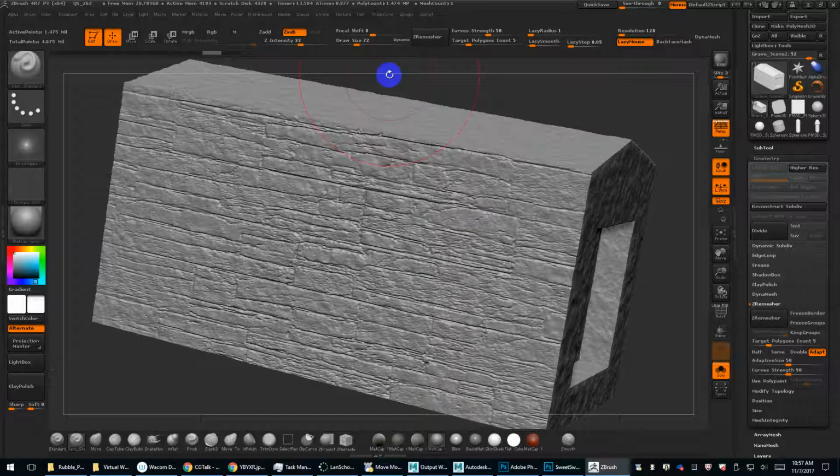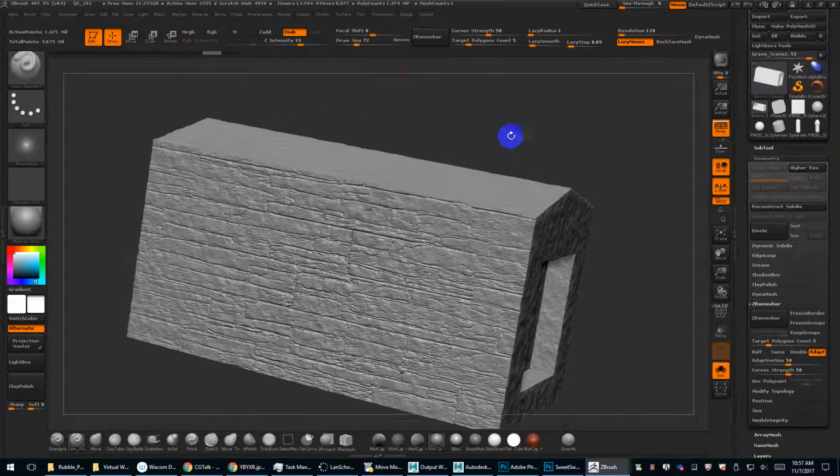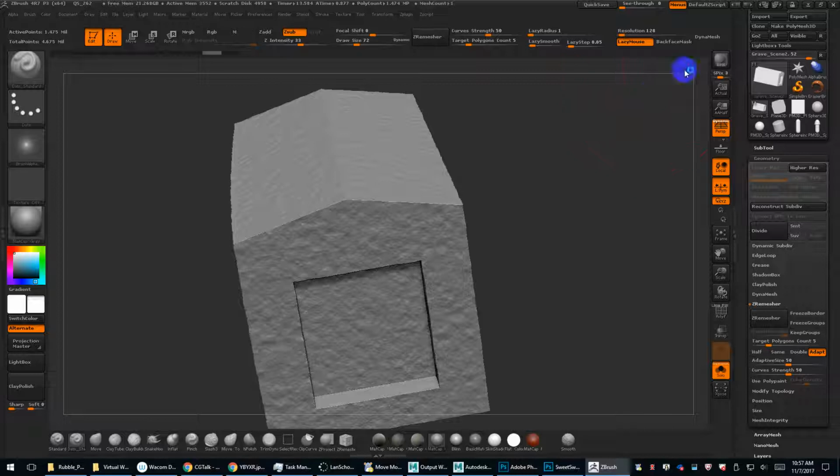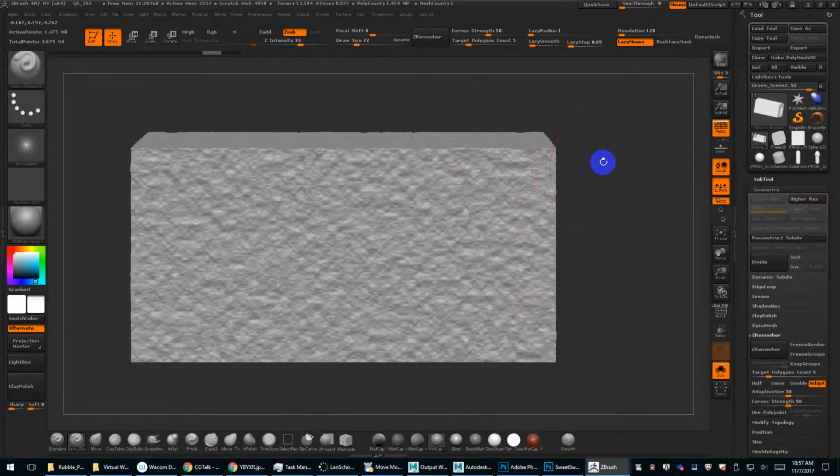So if you find your scene getting really, really slow, and even if you're hiding parts like a building or one of the props in your set and it's still getting kind of heavy, again, I always save a version. So I'd say version 3 of the scene, and then immediately save version 4, and then do the decimation, because you always want to have at least a base copy of those objects pre-decimation, because once you decimate, it's hard to get that detail back. So yeah, always make sure you're saving versions. Like any of my projects is multiple versions.